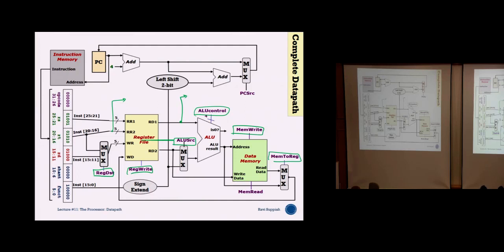That's why they will go both ways, but in the end it will only be one. But this one is not used. If it's an immediate, the immediate will come here, so we'll straight away extend it with 0, 0, 0 in front. Then the multiplexer here decides which one to select for the ALU operation: is it the register data or the shift data? Then they will come here and calculate.